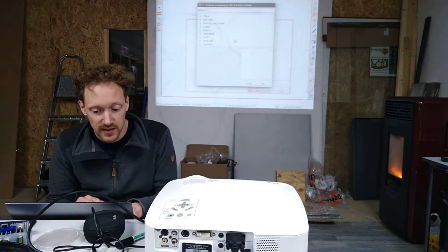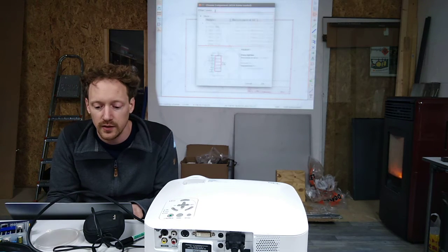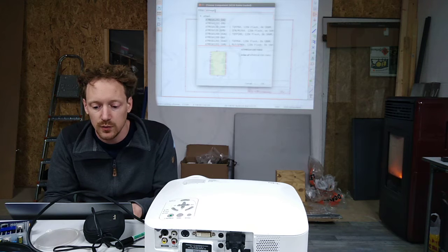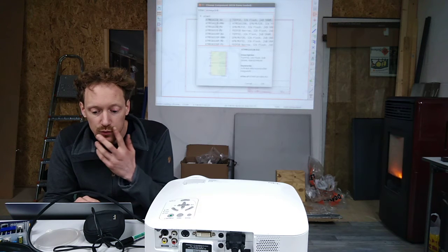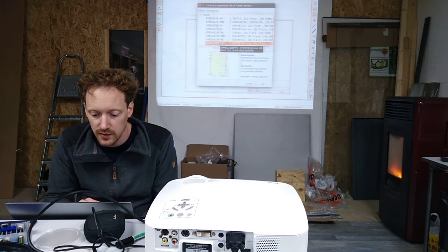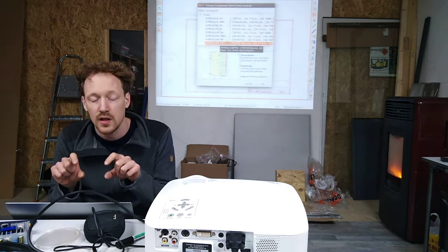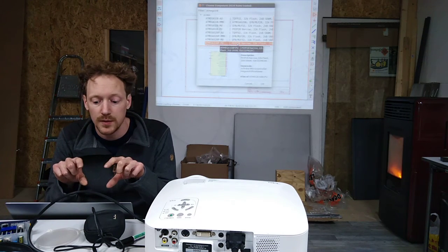So we press the A button, and then you can choose a component, and we can type here. We want to have the ATmega328, and I think I chose the 328P, which has a PDIP, so it has 28 pins.